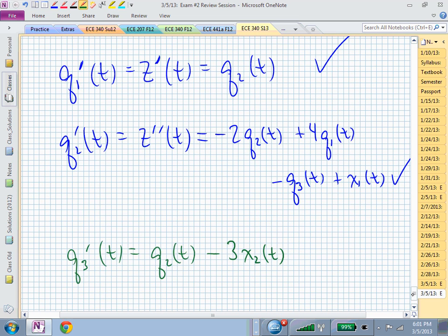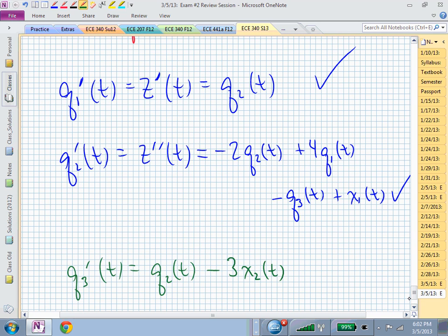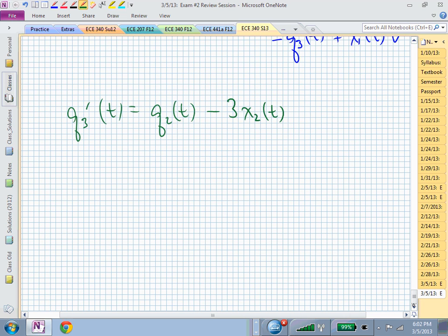Is it clear now what our state space dimensions need to be in terms of matrices? What's our system matrix? How big is the A matrix dimensionally? It better be square, doesn't it? And it's 3 by 3. It has 3 rows to give us something compatible with Q1 prime, Q2 prime, and Q3 prime. And now we can build that up.